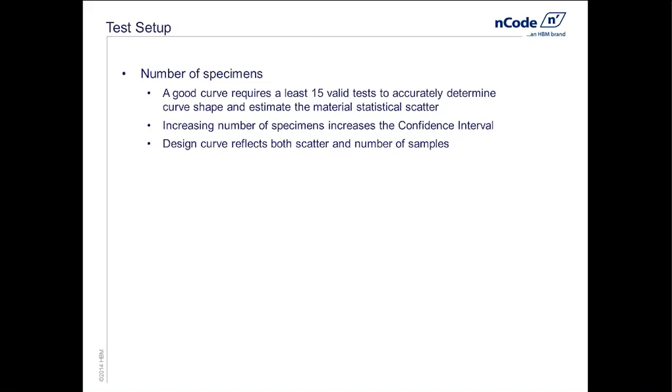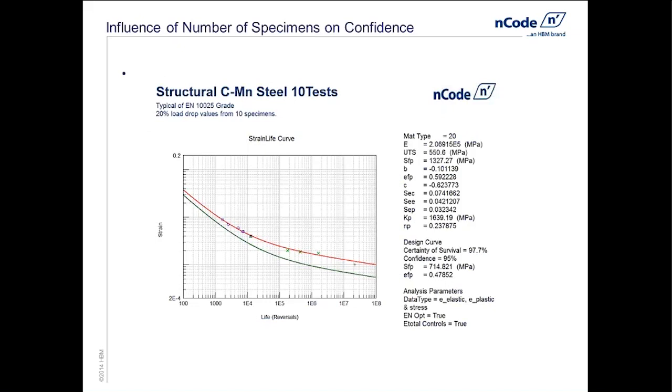And what I mean by that, here I have an example of a stress-strain-life curve, and if you look at the plot, the data points, both the blue diamonds as well as the green X's, are actual test data. These are actually specimen tests. The red curve is the regression of our stress-strain-life curve through that data. And you'll see there that we actually have scatter. Obviously, there is variation from specimen to specimen, even if they were at the same strain level.